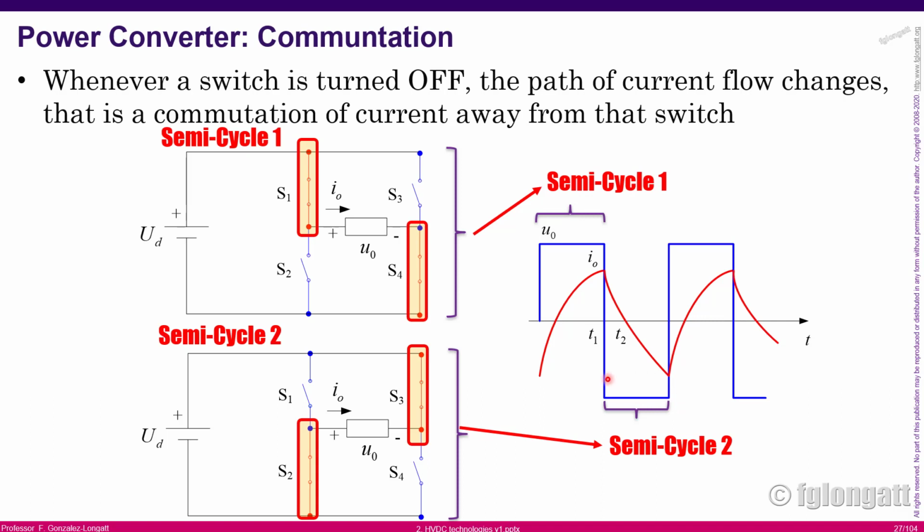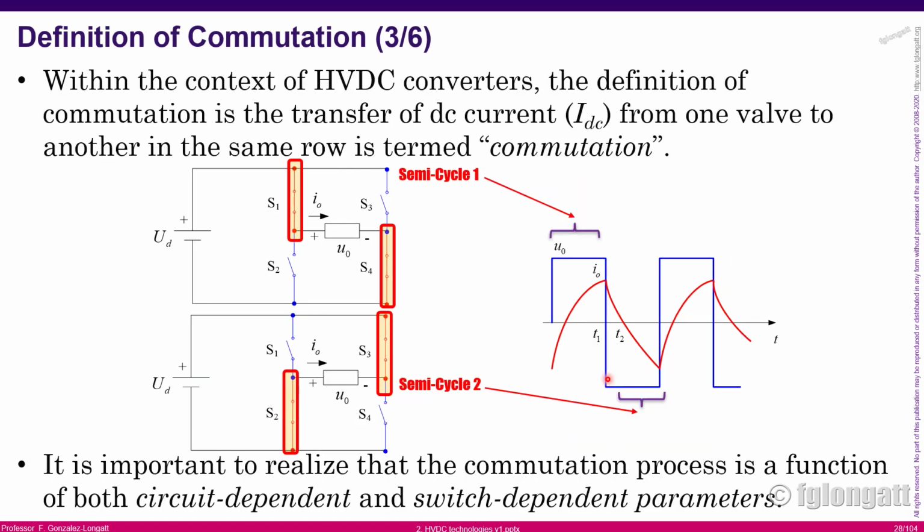Now, as you can see, if I select the appropriate way to open and close those switches, of course, we will have an appropriate sequence of voltages and currents, and these will be periodical signals, okay? And that is the idea. The term commutation comes from opening and closing those electronic devices. And when we have those closings and openings, we have some current moving through the load, and that is the most important thing when we are working with HVDC.